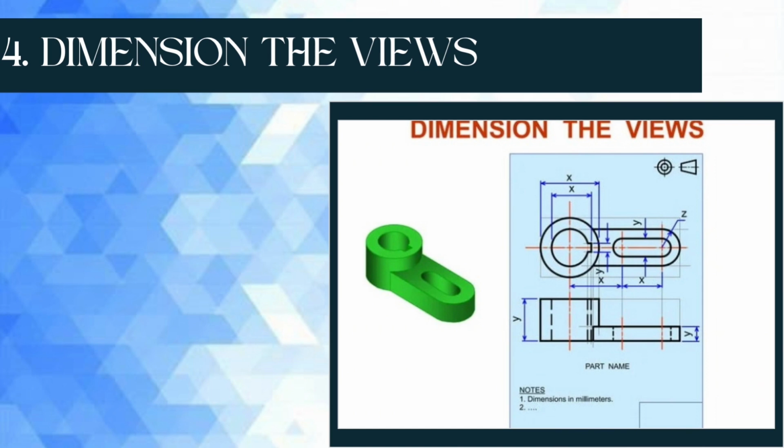The hidden circle will not be seen from the side, so you will not be able to see the hidden features. This cut will also be invisible from this side, and from the front view it will be shown with hidden lines.